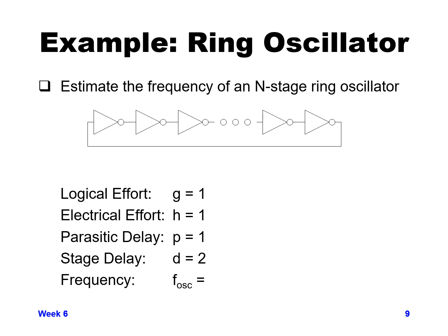So the delay through each stage is, again, normalized delay to a basic inverter with no load. Our delay is 2 for each stage. And since there's capital N number of stages, it takes us d times N to get through a full ring.